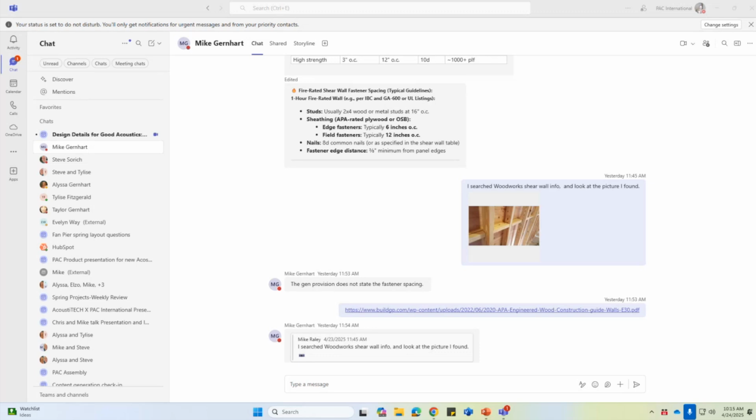So in that case, there are some very clear distinctions between them in terms of how they're used. In acoustics, I often see people using, specifying, recommending, and this often comes from internet forums and things like this. I see this a lot less from the professional acoustical consulting community. But I will see that mineral wool is often thought of as providing better acoustical performance. Typically, if you put it in the stud cavity of a wall, using mineral wool instead of fiberglass will give you higher levels of sound isolation from one side of the wall to the other.